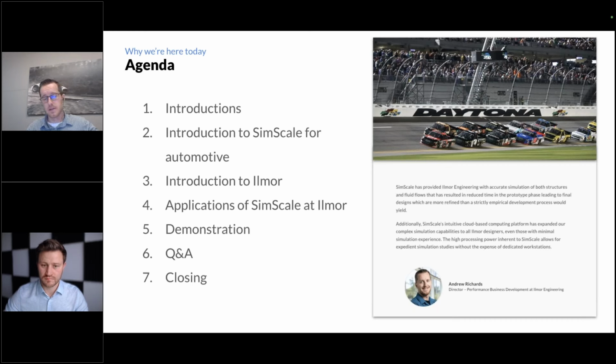I think we'll also see the use of synthetic fuels as opposed to crude oil based fuels. Again, in IndyCar, very near and dear to us here. They're using sustainable fuels, the 85 with a 15% gasoline blend that's sustainable or sourced synthetically. We're seeing that in other areas as well. So I think a bit of hybridization, a bit of synthetic fuels, and further refinement of both internal combustion engines and electric power units coupled to those engines, I think is what we'll likely see here in the next 5 to 10 years.